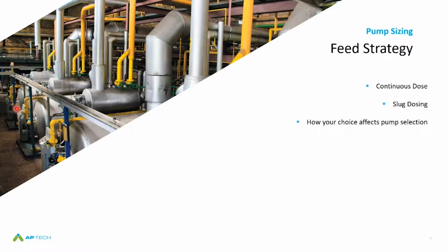You have a set point, and you're feeding that chemistry based off of your set point. The chemical controller is going to monitor, and it's going to dose chemistry appropriately. And then you also have PTSA, which works the same. You have a set point and the sensors measuring the fluorescence of the tracer that's included in the scale corrosion inhibitor specifically, and it's going to dose that chemistry according to what it's seeing and what it needs to be.